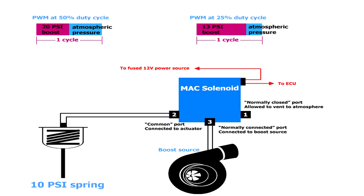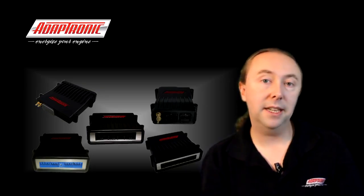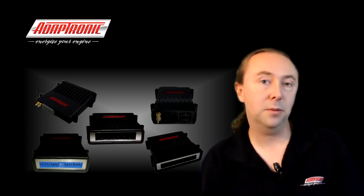So that means that with 50% duty cycle on the valve, you'll end up with double the boost of the spring. Another example is if you set the duty cycle to 25%, you'd end up with 13 psi of boost. Now in general you'd pulse width modulate the solenoid valve at about 30 Hz, that's what they tend to like.